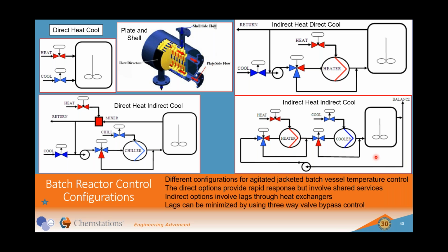These invariably are using heat transfer fluids. So this particular one is our preferred method, because if you get a breakthrough from any of these services into heat transfer fluid, as you probably all know, it can be quite difficult trying to source where the leak's coming from. At least if you have a reactor system, maybe you've got 10 reactors in the building, it enables you to isolate the leakage much quicker with that approach.